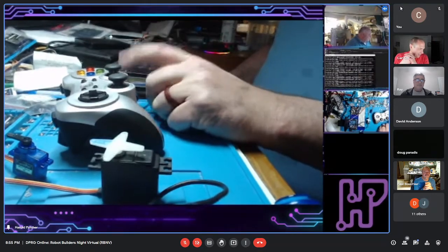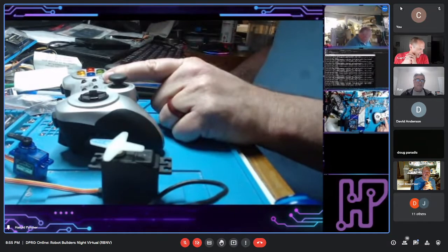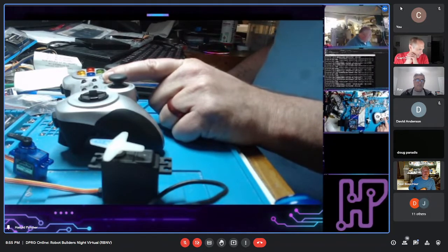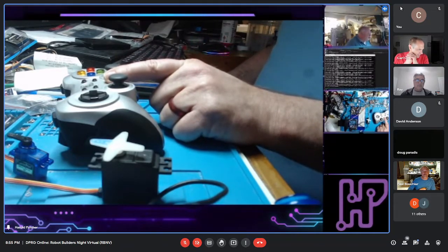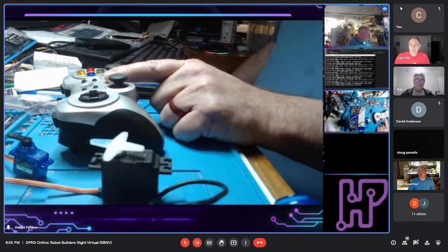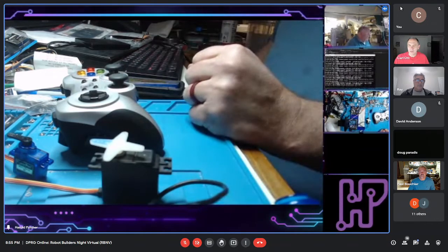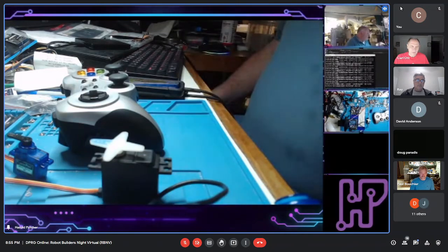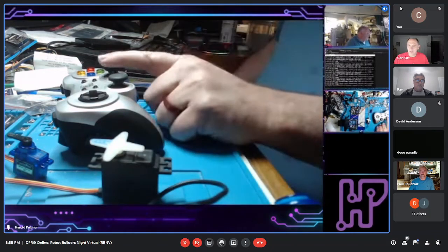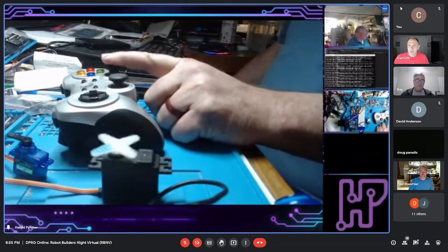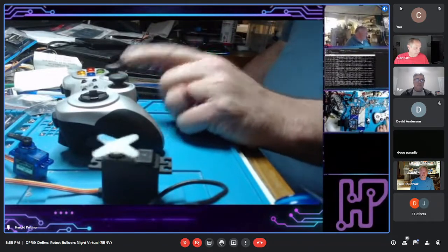This is coming through the standard nodes that come with ROS built in, that's been configured, going through my Ackerman node, which doesn't do anything but just pass through right now, down to the servo node, which figures out what the limits of that thing can be, and then talking to the servo driver node, which then actually sends down the correct angle to the right thing as I go. So that's all I got really.